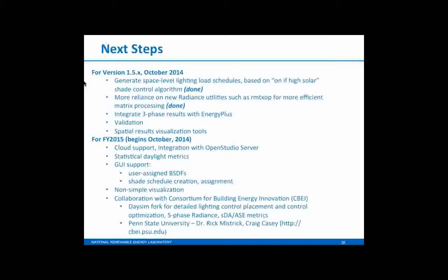Well, now you take each one of those exemplar models over to Rick's project, do some really, really detailed glare and photosensor analysis that gets that right, and then pass that back to the source OpenStudio model, which can then go to EnergyPlus and give you a truly integrated and optimized whole building result. Whew! Okay, so that was the Radiance stuff.